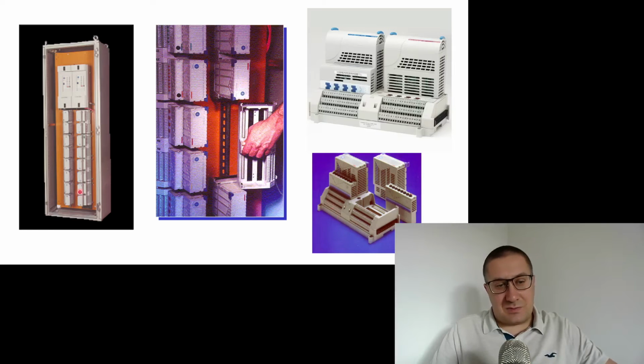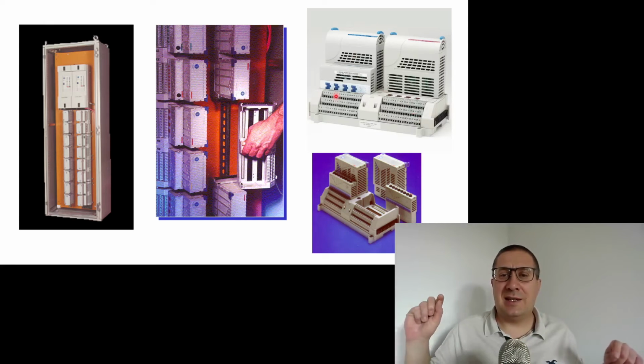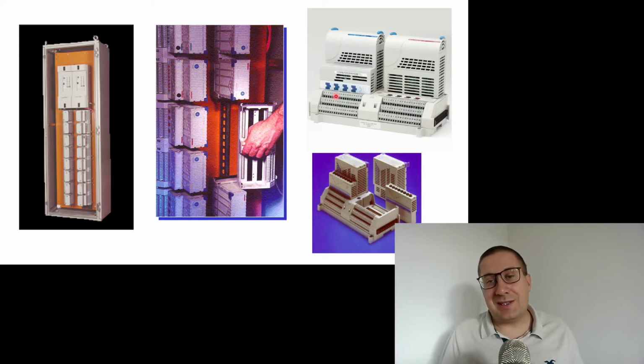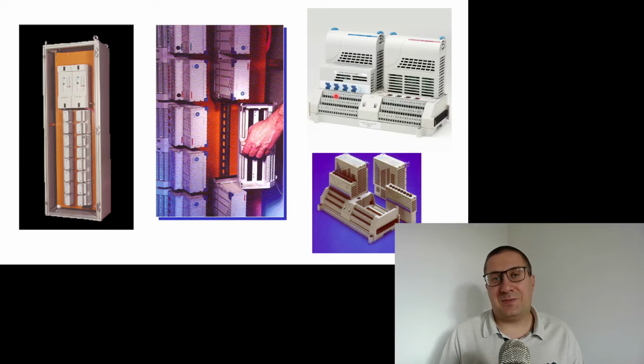So here you can see two controllers and I/O modules. You can unplug the I/O module and then plug it again. Generally, it looks like this. So if you plug the cable to the pin, you need to register it in the system. So you need to say that the I/O module number, I don't know, 26, the pin number, I don't know, 17, this is the temperature of the steam, right? And we should associate the name with this. We can set some alarms, etc., etc.